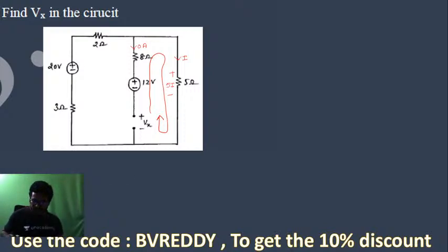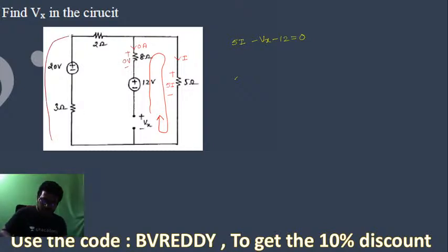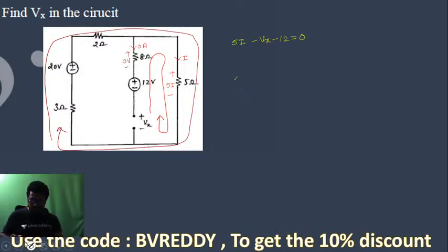Tell me, if we apply the KVL in this loop, what will we get? 5I minus Vx minus 12 equal to 0. In this resistor, there is no voltage, 0, since current is 0. Now to get this current, I will apply the KVL to this outer loop. So this Vx is equal to 5I minus 12.